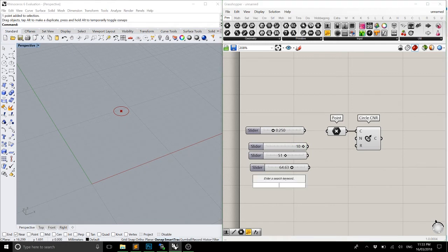And then the final little shortcut is if you were to say, let's say, 8.24 is greater than 87.54, that will then create a number slider with those two as the minimum and maximum. So it's just a quick way of actually controlling almost every variable you have there. So a lot of information on how to make sliders, and I'll probably stick to the one that goes to 10 for the radius.